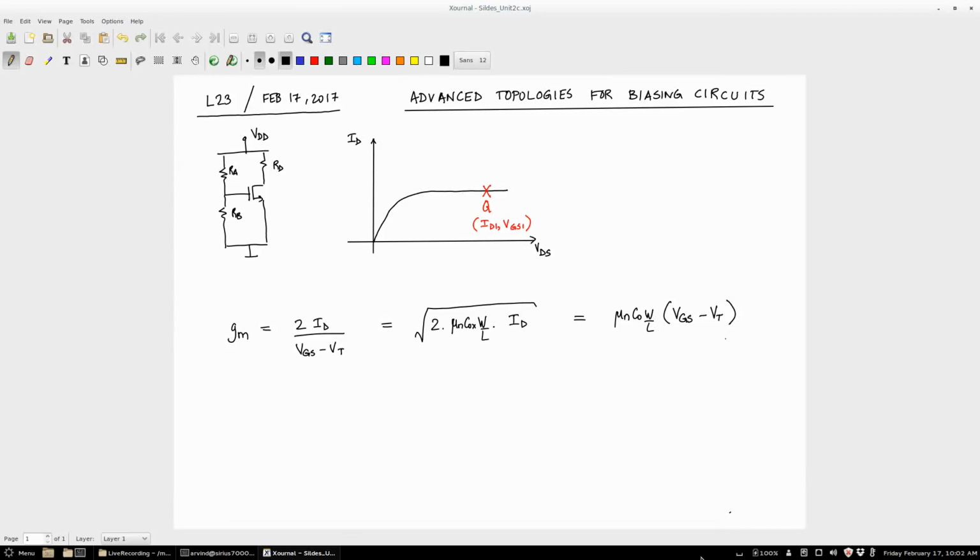Say for some reason, and I can tell you the reason also, you have experienced this reason also, a manufacturer makes thousands of transistors. If you take 2 transistors, nominally they are the same number, both are BC177, right? But will they have the same value of the various parameters? Can never be like that, right? VT will be nominally say 0.5 volts, but the manufactured values fall in some range around 0.5, just like resistors. You had 1k, it may mean 0.99 to 1 point something, correct? So there's a tolerance in everything.